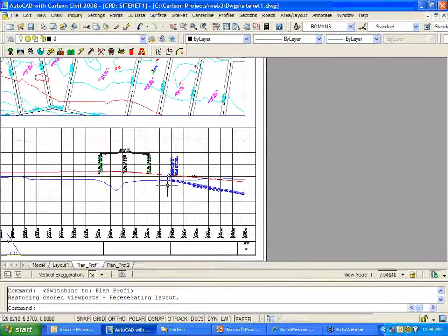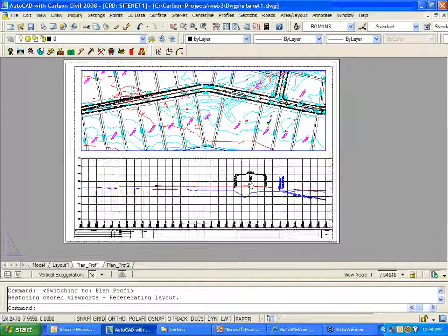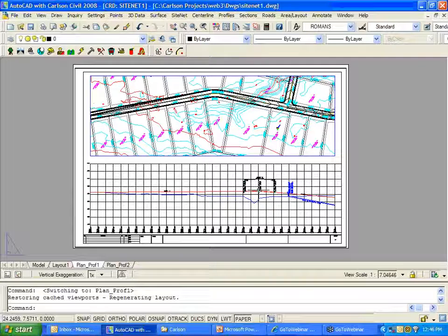So I did want to show that. It's really quite straightforward. A couple of steps in there to be aware of. Once you create that network, that sanitary network, or storm, or whatever it may be, you want to link it to that road center line. You want to generate a centerline file of it, and generate a PRO file of it. So a couple of little steps in there, but basically it ties it together quite easily. And I think that's about all I have to show. Again, the key was to show you how to generate plan and profile sheets with our software.